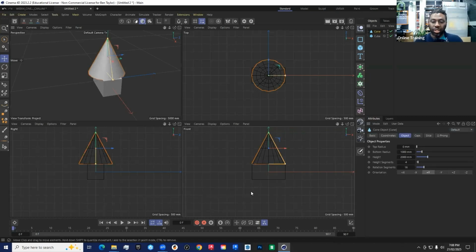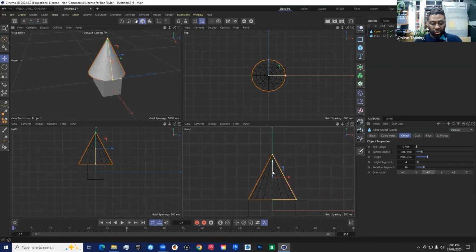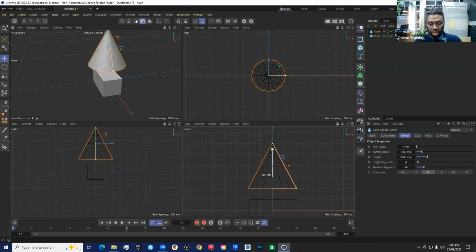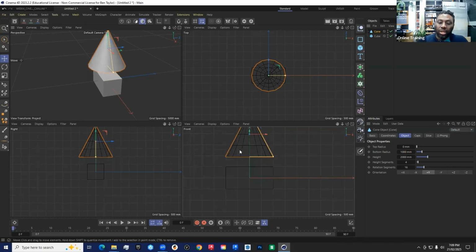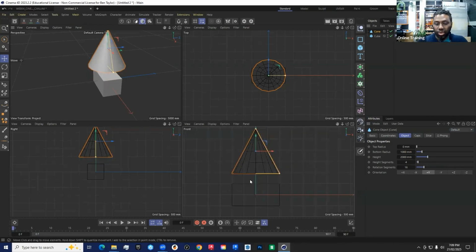They all work simultaneously. So if I select this object, it is in the right place, but if it wasn't, I can hold down Shift and I can move it to where I want it to be. If we have a division which isn't divisible by 50, we can move an object by as much as you want it to and get it to snap to other objects.